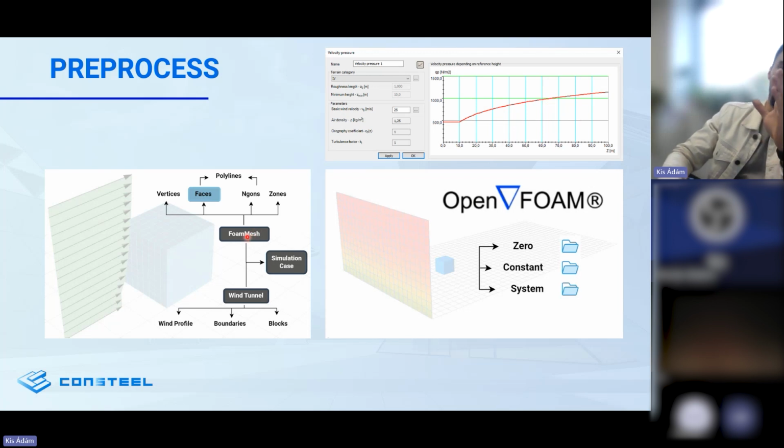I will talk about this later. What does it mean? We create this virtual wind tunnel with its wind profile according to Eurocode, with its boundaries and a few blocks, a discretized domain where we are introducing our building. So this is the simulation case.